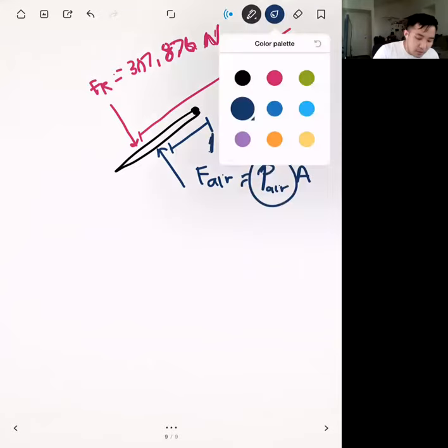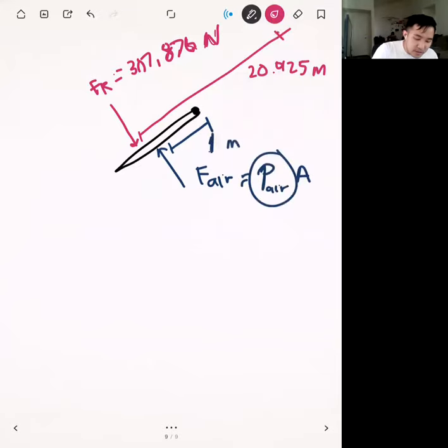And so the last part of this problem is, now that we have this distance from the surface to here, we need to compute the distance from this force to the hinge. And so we want to get that L dimension right there. The way that we're going to do that is that we know that this distance right here between the surface and the centroid is 20, because we know that the y-coordinate of the centroid is 20 meters.